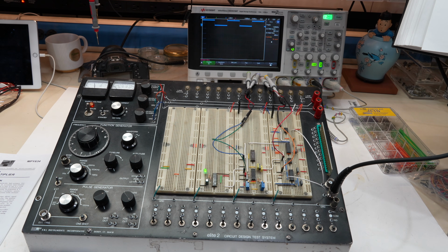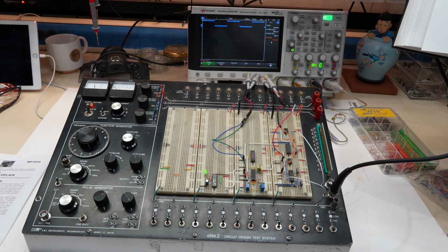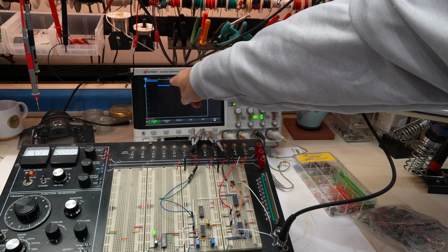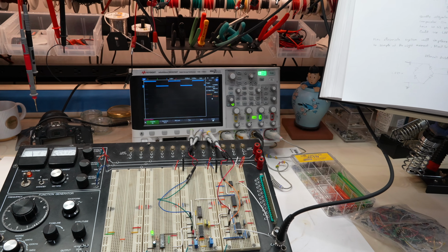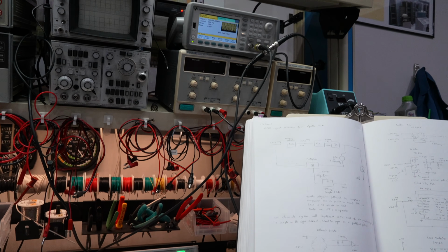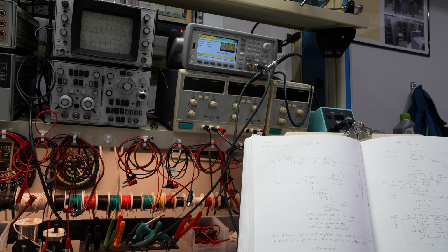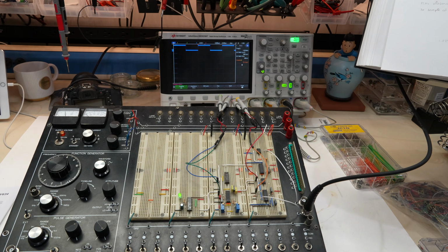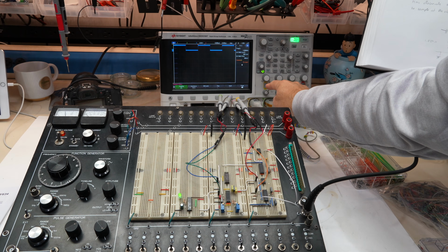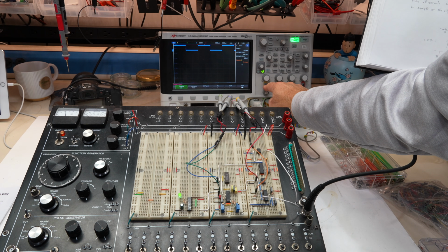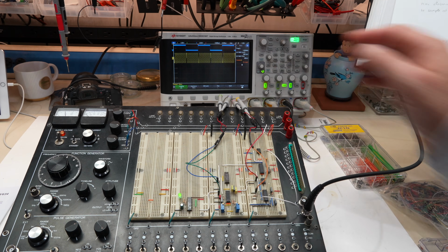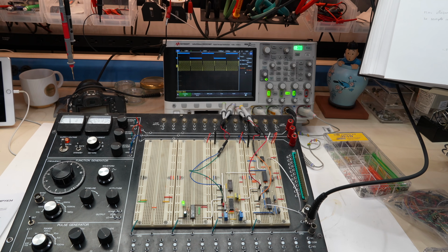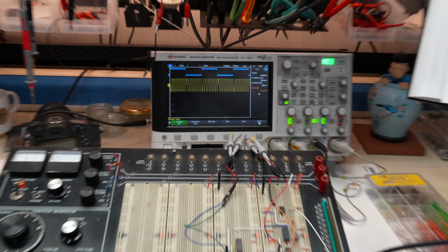Alright, so while Mike is figuring out the digital decoding of the bits, I am doing the hardware decoding. This would be the bits that the telemetry PCM is sending. I reproduced them with my little HP oscillator there. And the way they do it, they use BPSK, binary phase shift keying, which is a big word to just say that they change the phase of the signal every time the bit changes.